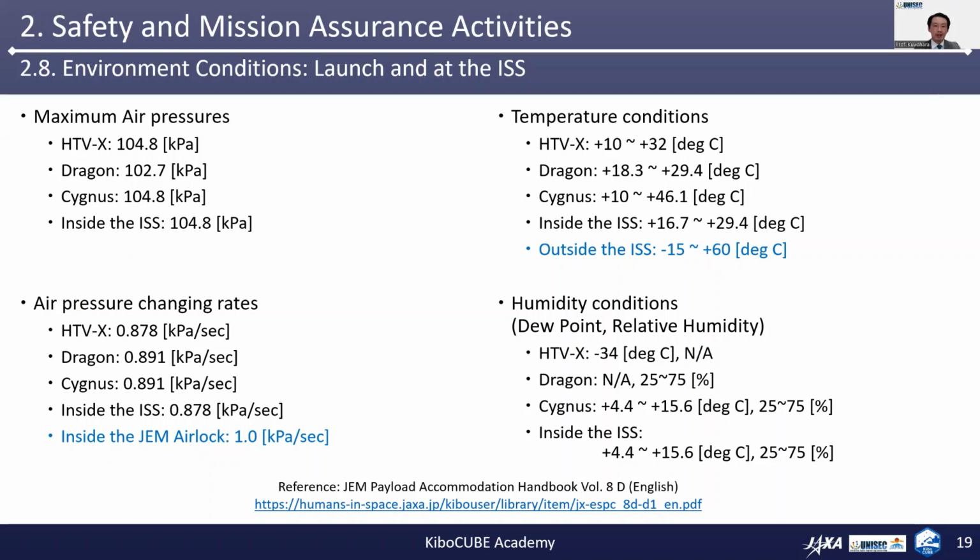So your satellite structure needs to have venting holes for venting out the atmosphere inside the satellite during the vacuuming process. Another important aspect is the temperature condition outside the ISS, while your satellite is inside the J-SSOD, awaiting release from the ISS.